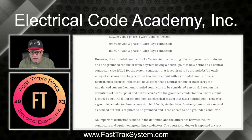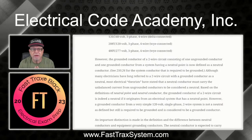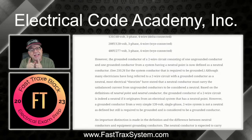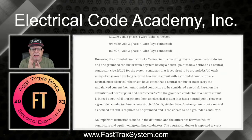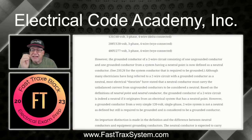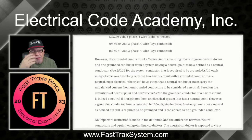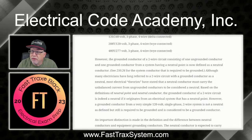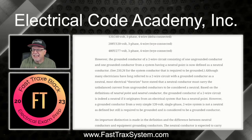Okay. Well, in a black and white circuit, ignoring the equipment ground right now, just the black and the white, whatever's going out, let's say you have 10 amps on the black, then you're going to get 10 amps on the white. It's alternating current, but again, it's going to have it. So is it carrying the maximum unbalanced load? No, it's carrying the load, no different than the hot conductor, the black. So the purists say, well, it cannot be a neutral, but it is a grounded conductor.